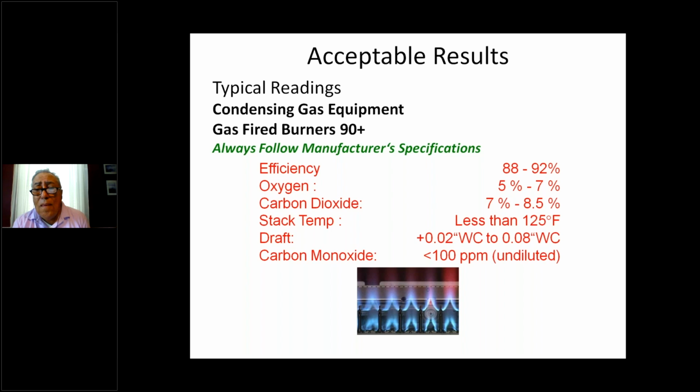Very good. And why are manufacturers of atmospheric boilers that offer 89% efficiency, or for residential applications, even 91% efficiency, are they using a different efficiency than the commercial high efficiency condensing boilers? Well, we're looking at apples and oranges. It's two different types of technology.